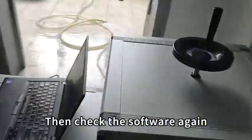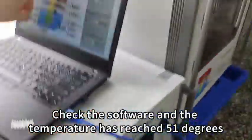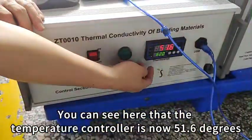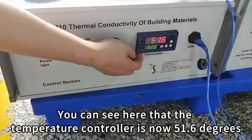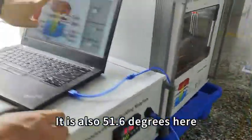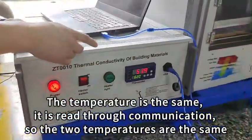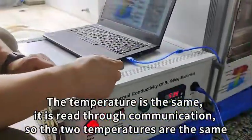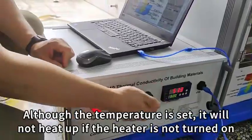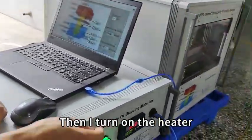Then check the software again. Check the software and the temperature has reached 51 degrees. You can see here that the temperature controller is now 51.6 degrees. It is also 51.6 degrees here. The temperature is the same. It is read through communication, so the two temperatures are the same. Although the temperature is set, it will not heat up if the heater is not turned on. Then I turn on the heater.